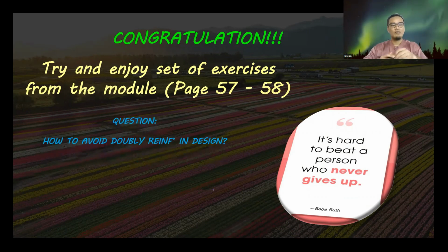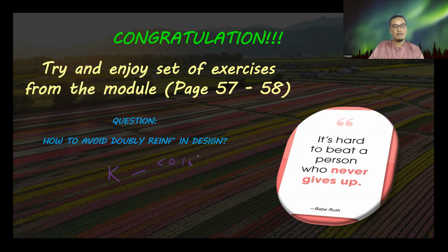However, I have one question for you. In your opinion, how to avoid doubly reinforcement in design? Any answer? It depends on the value of K, either lesser than 0.167 or greater than 0.167.